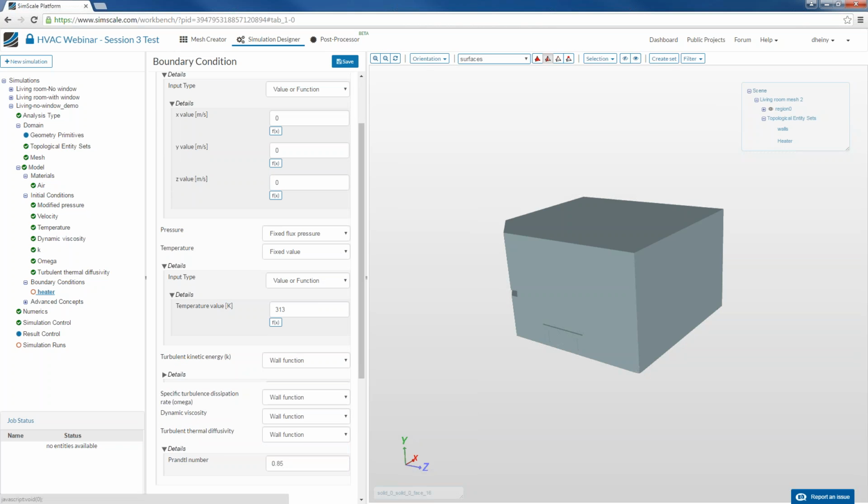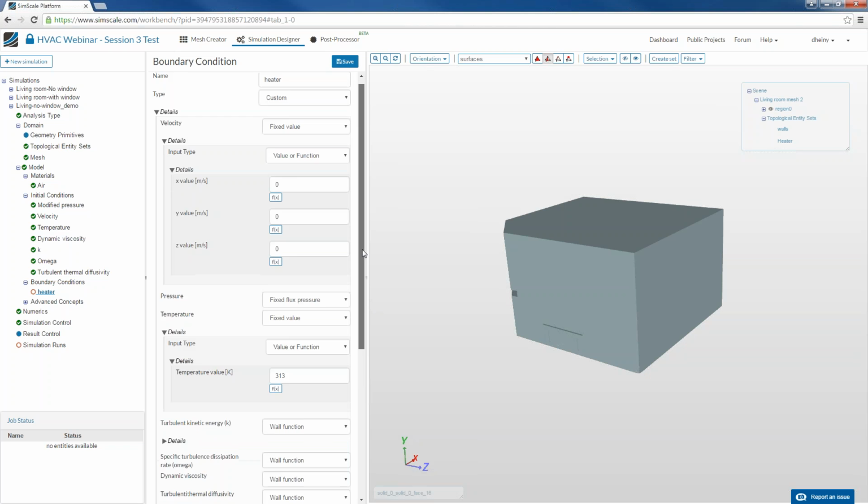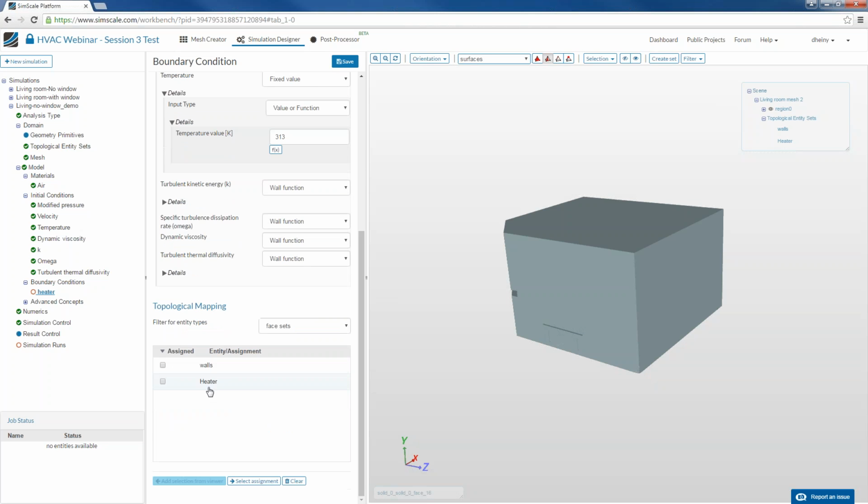The good thing about these wall functions is that they don't have any parameters, and it essentially comes down to turbulent modeling that we don't cover today, but these wall functions are sort of the standard boundary conditions that you use at the wall whenever you're dealing with a turbulent boundary condition. There's a little bit more theory to this, but we won't cover that today.